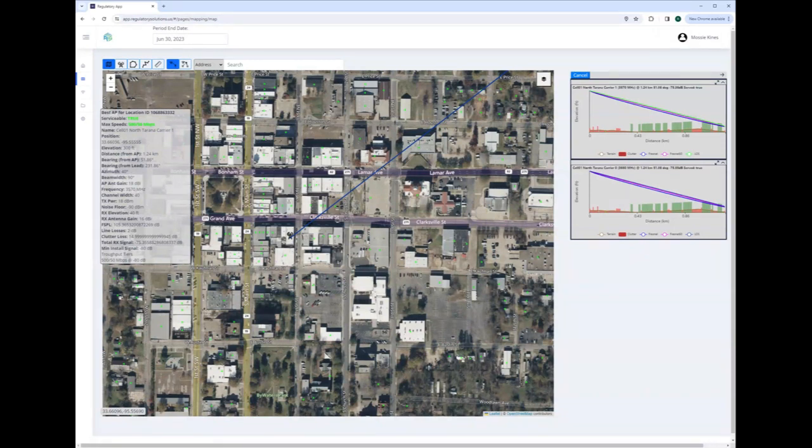And all the information from the profile is in here. So this is showing you your distance, your bearing, both directions, right? The azimuth that AP is pointing, the beam width of that antenna, the gain of this antenna, the frequency, the channel width, its transmit power, the noise floor that you've set for this, the RX elevation. So he has this at 40 feet, the gain on the receiver side, our free space path loss, any line losses.